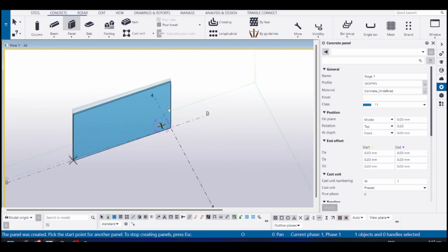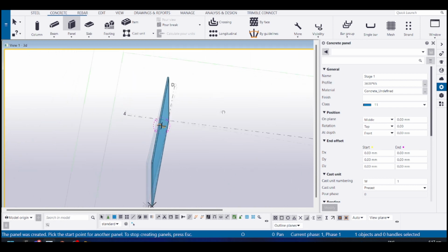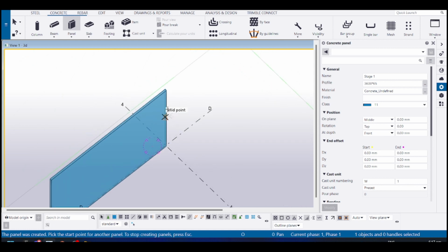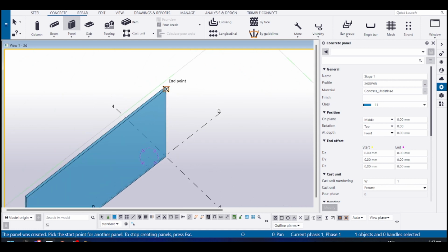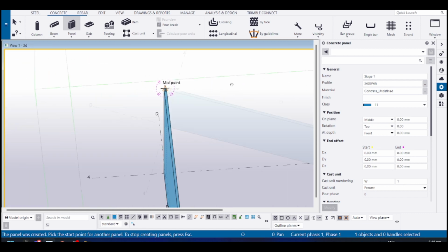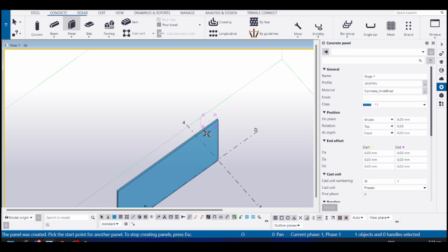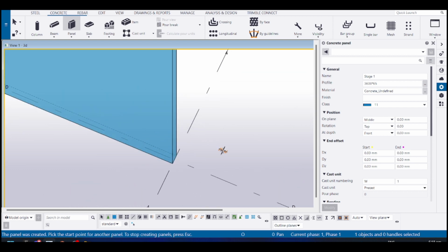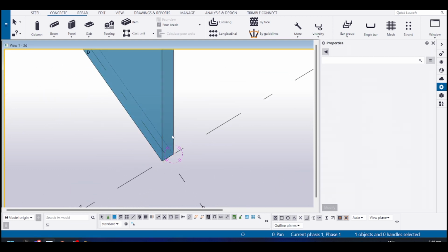Yeah, this is the setting that you need in case your views are not functioning correctly. The object that I select that I have my mouse on, and then I press the middle button, it will take it as the pivot point. Okay, so I have this wall here now, and it's basically aligned with the center now.